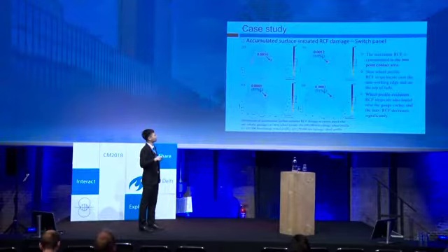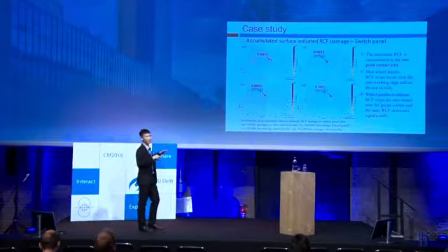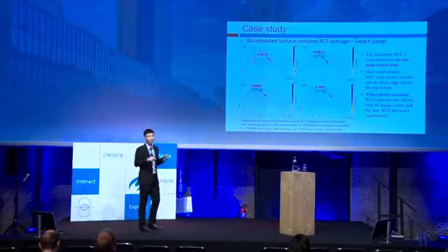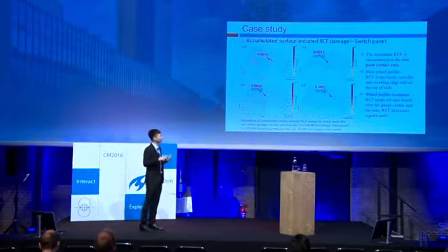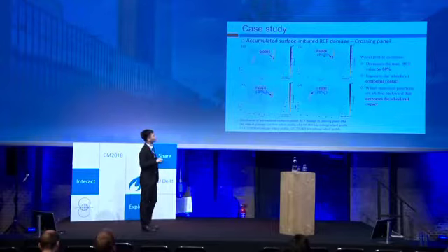With wheel profile evolution, we focus on figures B, C, and D. The wider RCF bands are found not only on the top of the switch rail, but also at the gauge corner of the rail. Basically, the point is that with wheel profile evolution, the maximum RCF value decreased by 91%. Meanwhile, similar conclusions are found in the crossing panel too. So we can draw the conclusion that when the hollow wheels are found on the wheel, the rolling contact fatigue damage may decrease.